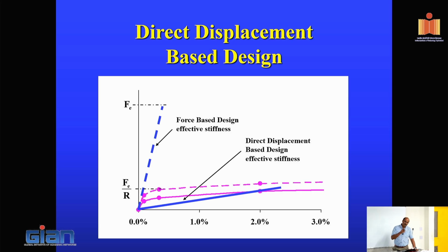The structure was also designed using a displacement-based design. I think a lot of people disagree with me or would get upset with me, but displacement-based design kind of allows you to use large R factors, basically. There's no way otherwise you can bring the force down. So it was done basically to show you can actually use lower forces and still provide resistance adequately.